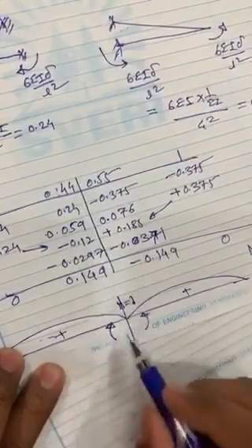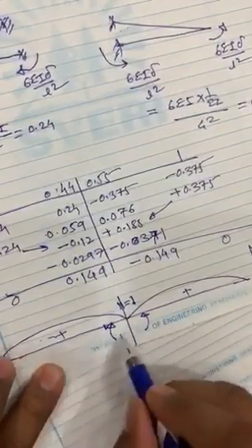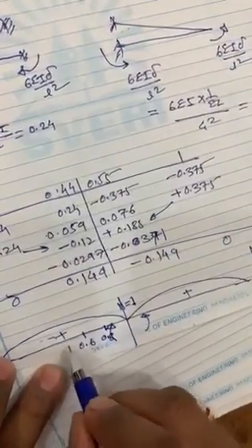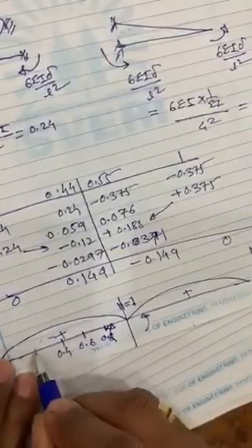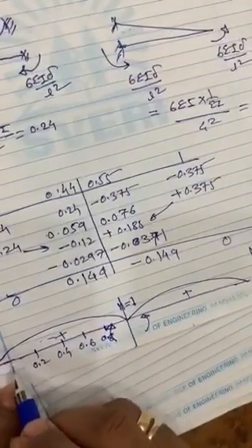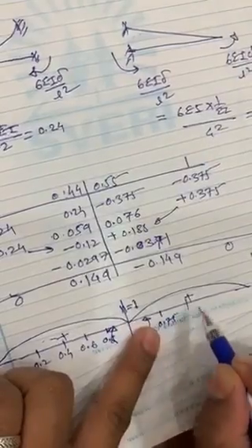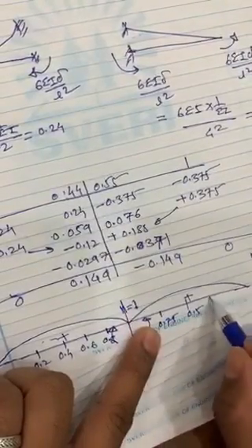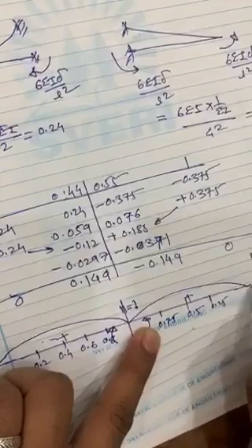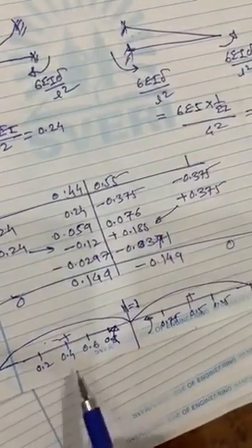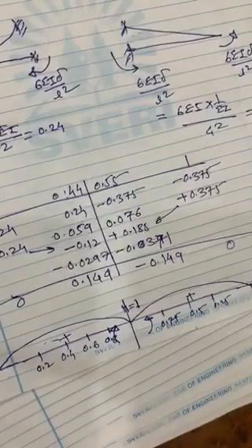Then you can start with n equal to 1 here because the moment is applied. There is a 20% interval, so n is equal to 0.8, n is equal to 0.6, n is equal to 0.4, n is equal to 0.2, and 0. Similarly, on this side a 25% interval: 0.75, 0.5, 0.25, and then 0. And for these intervals we have already calculated the k values.